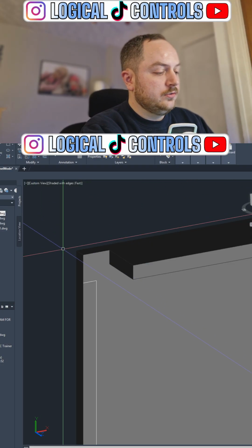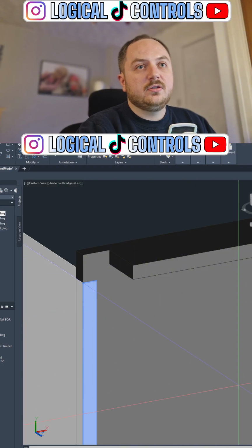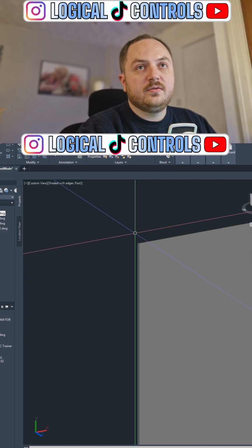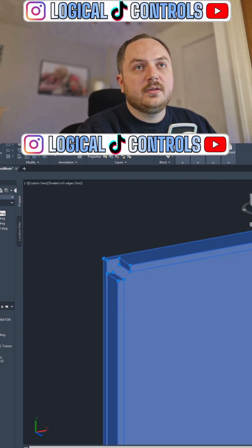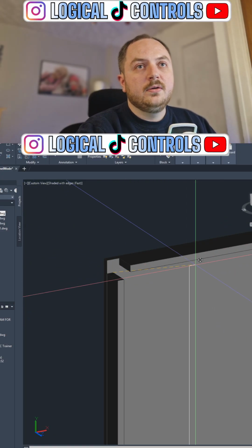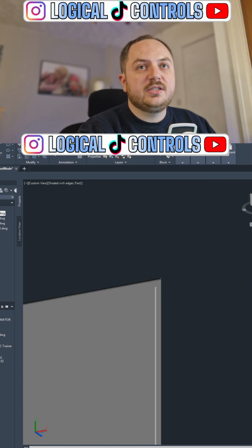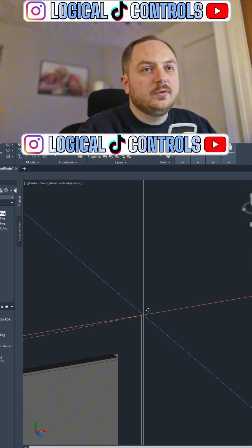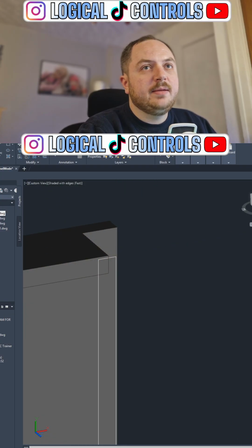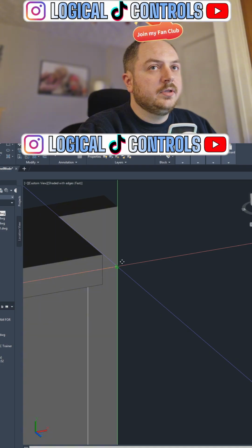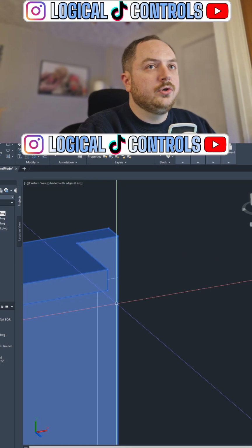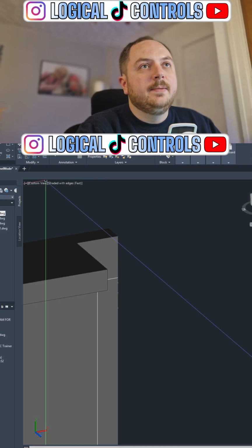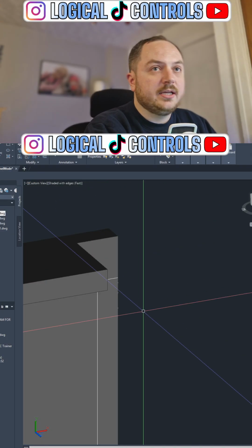Okay, so let's press pull that. There's our return fold for this edge. I think I made them 5mm. Yeah, I did. And then we're going to do the same for the other edge. So these return folds that I'm doing, they're not necessary for the model. Any metalwork company who knows what they're doing would know to put return folds anyway. But I'll show it, and I can explain why.